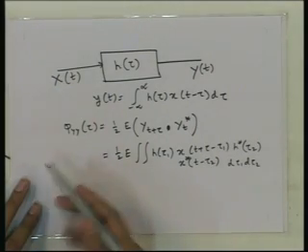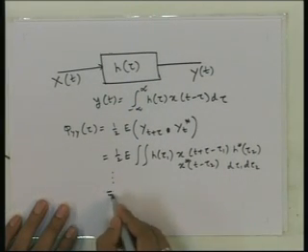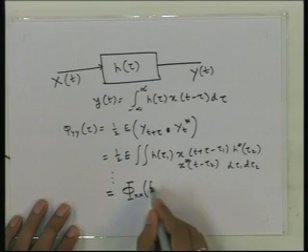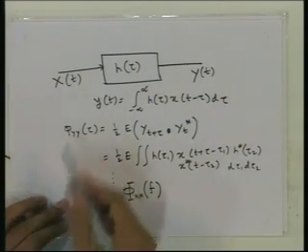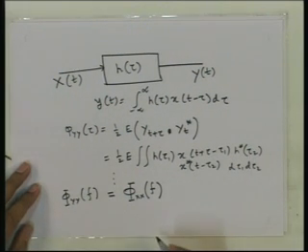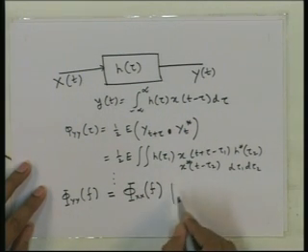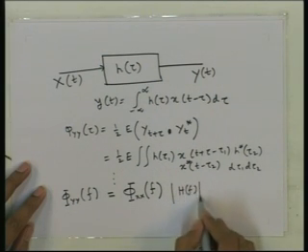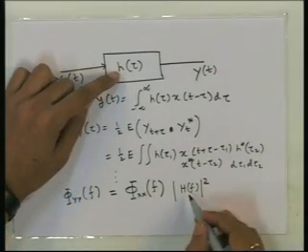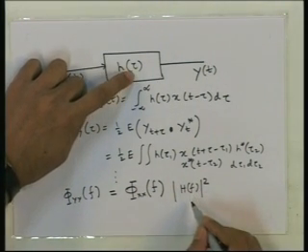So, we can take this and find out the Fourier transform. We have to take another integral, and with some manipulation one can show that the Fourier transform of this, that is phi_yy(f), will be the power spectral density of the input process times |H(f)| squared. H(f) is the frequency response of this system, that is, the Fourier transform of h(tau).